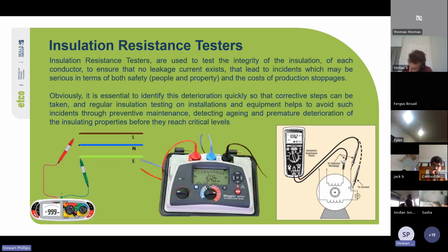Sometimes you don't need an insulation resistance tester to identify that wiring has gone bad. I've had a couple of jobs when I was doing resi maintenance where I just used my multimeter across the mains, phase to neutral, and I was getting straight continuity, dead shorts in several locations. There were no appliances plugged in, everything was switched off, and all of the light bulbs had been taken out. There was nothing that could have been causing the short apart from damage to the cables. So those properties got rewired.